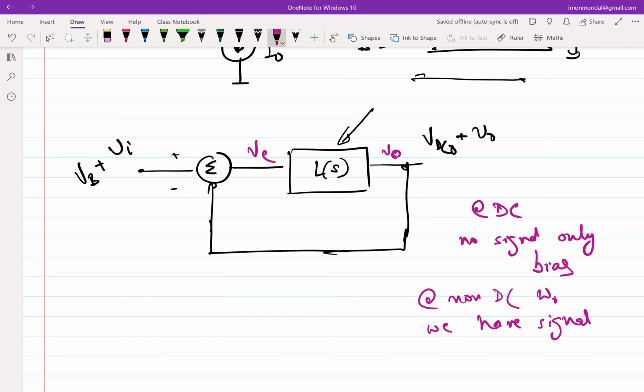This is similar to when you bias your common source amplifier with a decoupling capacitor and so on. You assume that at signal frequencies the capacitance is shorted, and at DC you are only setting the bias. Same argument. Now if we want to decouple this, you already know one way: you already knew how to bias a common source amplifier with a capacitor, resistor divider, and so on.